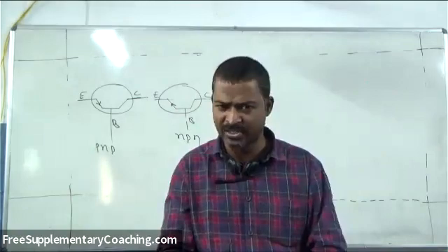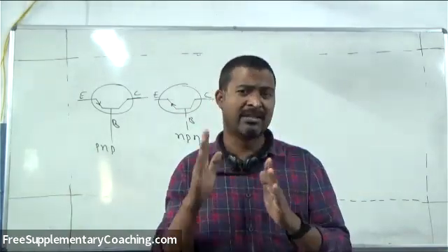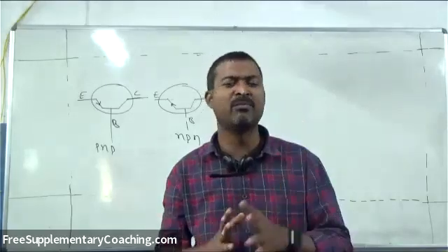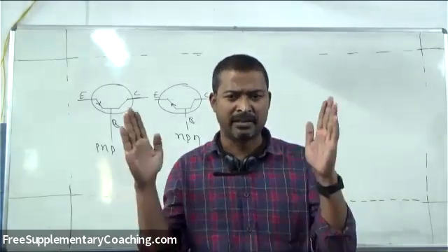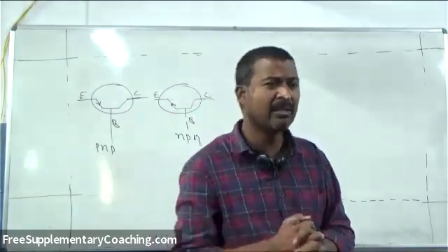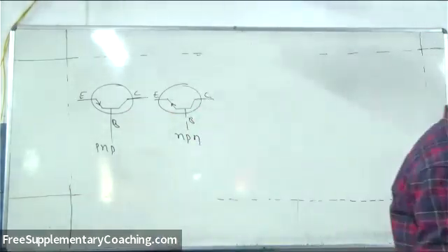Depletion layer. A PN junction diode is one P and one N type semiconductor joined together, a junction is formed, and we call it a PN junction. Due to this, N side positive immobile ions and P side negative immobile ions will be created. And this layer of certain thickness we call the depletion layer.